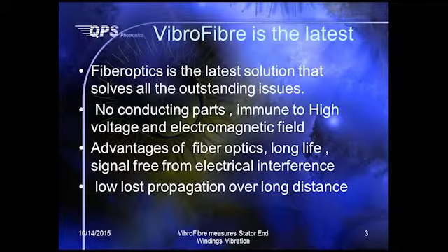What we have today, though, is the latest solution using fiber optics. Some of the benefits are quite clear. One, there is no conducting part, so there is no fear of inducing partial discharge, and it is inherently immune to high voltages and the strong electromagnetic field.